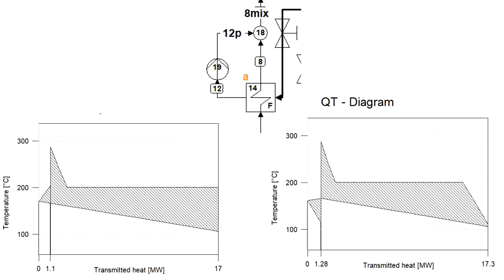Here we can see illustrative QT diagrams of the heat exchanger of the feedwater heater and of the following node. So first, on the left hand side, if we keep the condensate outlet at the saturated level, once we mix the condensate with the mainstream, our temperature increases.